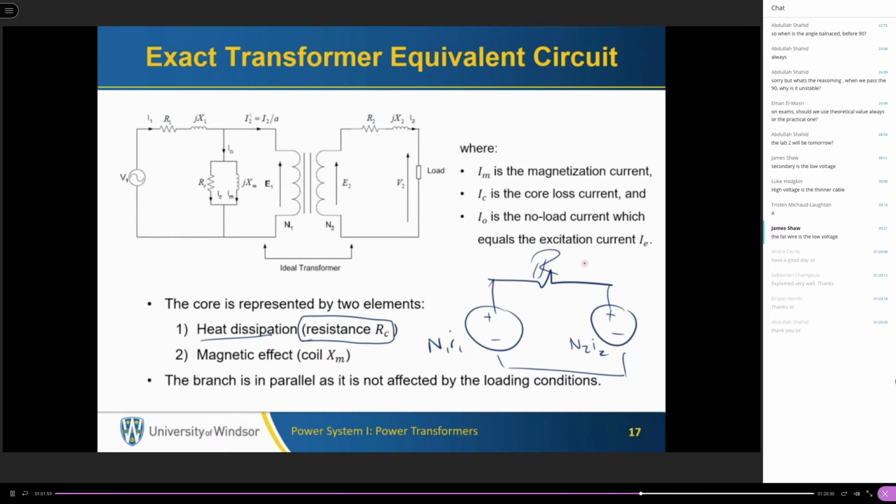This reluctance consumes part of the current in order to accommodate any losses in the MMF. There is a loss in the MMF across this reluctance, similar to a voltage drop. We also need a current component that compensates for this reluctance of the magnetic circuit of the transformer.